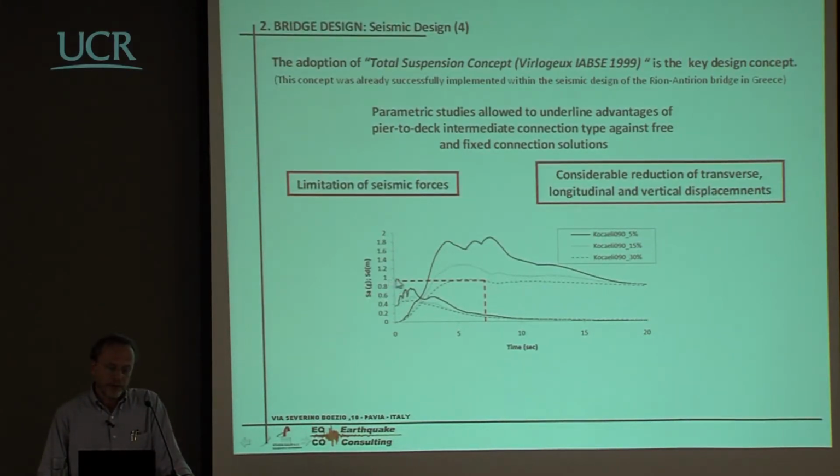Well, actually, this is the displacement demand of 1 meter, and you can see that you are essentially at the plateau level there. So you could in this case accept essentially any sort of period of vibration. And these things down here are just acceleration spectra, because this scale is giving both the displacement in meters and the acceleration in g.